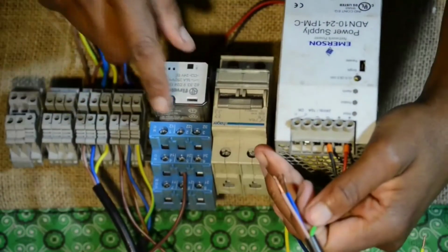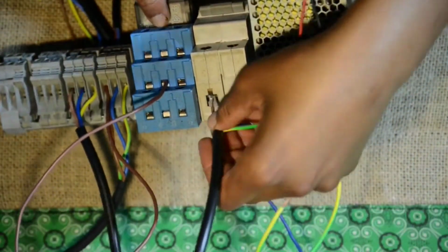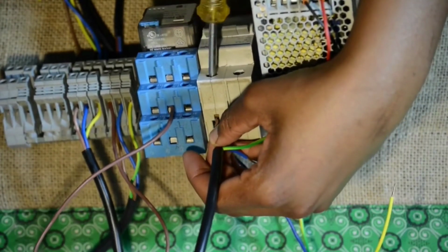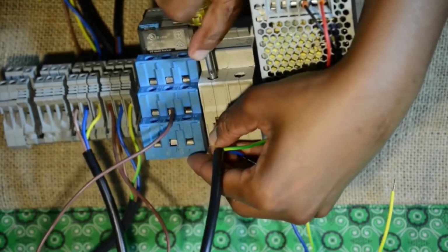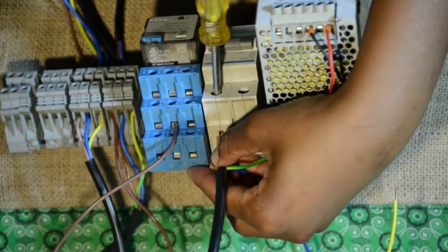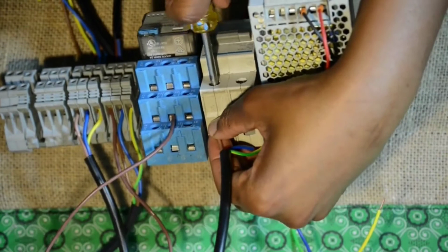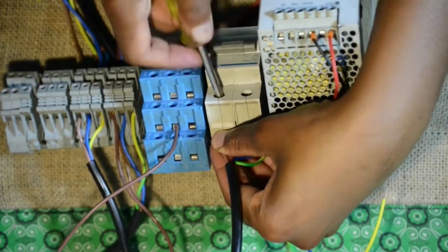So if we don't include this circuit breaker, what's going to happen is that we're going to have an emergency power source that comes on to a faulty circuit, and that is going to be tragic, especially if it's a short circuit. This thing is just going to heat up and it can cause a fire.